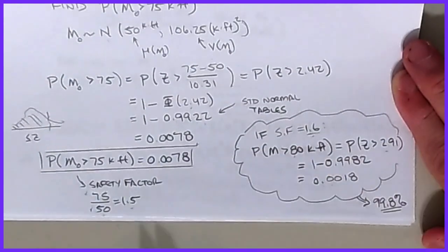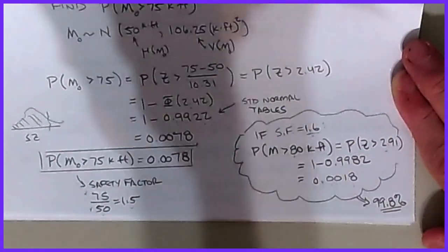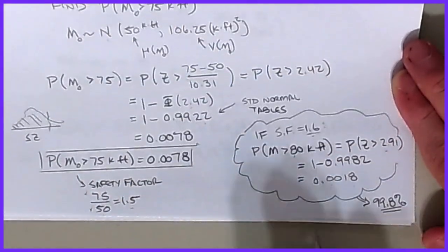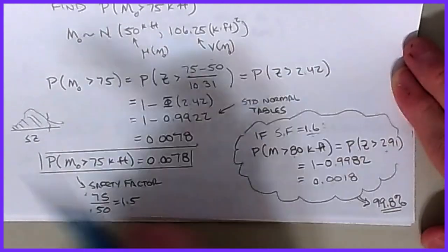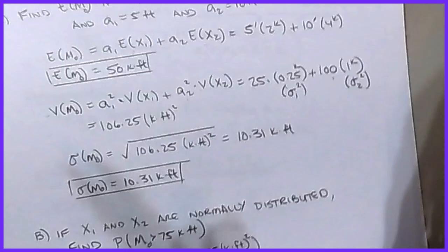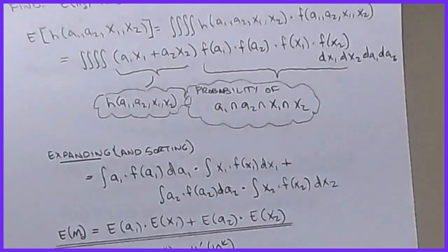Now, for other types of loads that are more permanent, like dead loads, your sigma would be something smaller, and you would have to include that as well. But this is just for a pure live load analysis case, and it's interesting to see that number show up. Okay, so anyway, I always find that kind of interesting. This is one of my favorite problems in this series, just because it kind of justifies a lot of what we do as professional structural engineers.